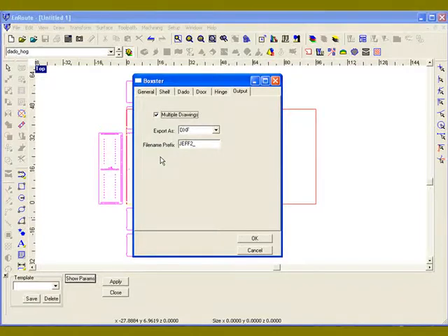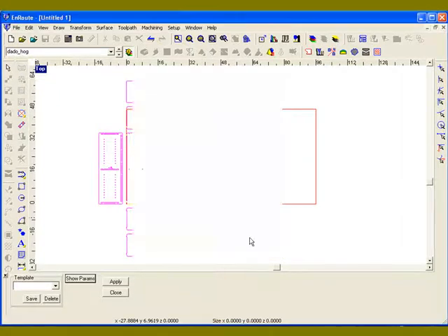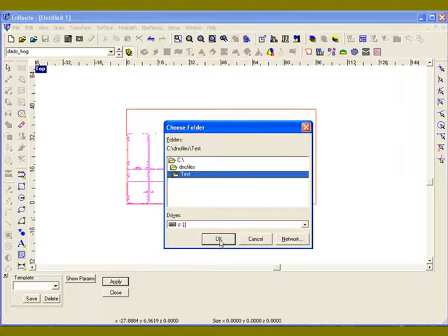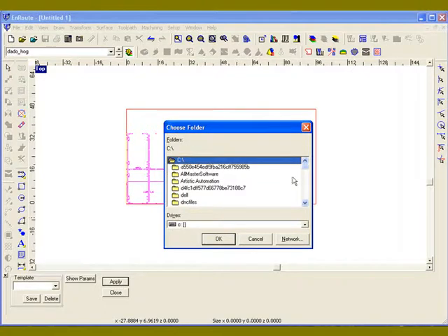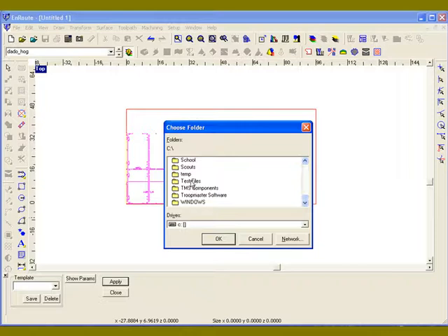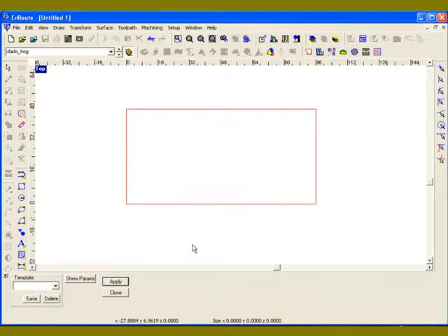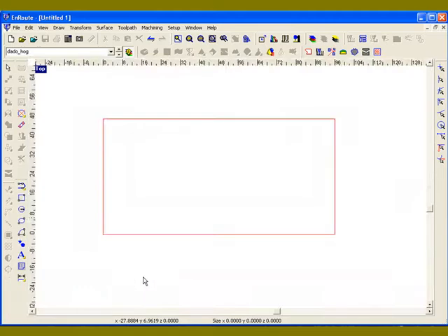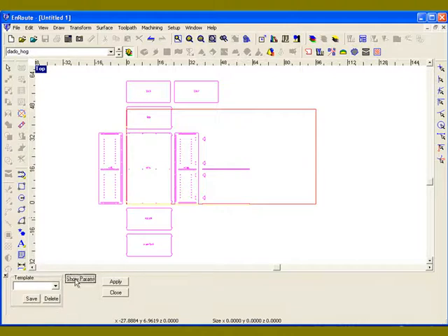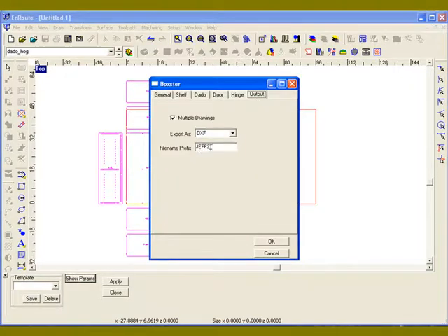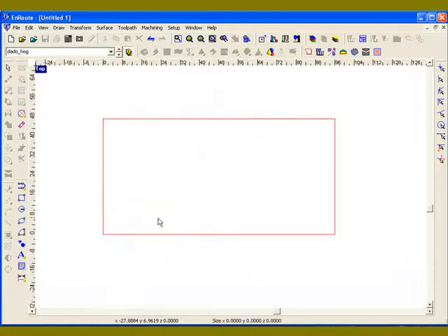It will allow me then to use the automatic toolpath engine to process the job. So I'm going to do the same here. Click OK, click apply. It's going to ask me where I want it, so I'll just pick a folder here. Okay, so remember I've got that in test files. Okay, so now the geometry's been created, and let's see if I remember. I called it Jeff2 underscore, so that's the prefix that's going to go on each of the names.